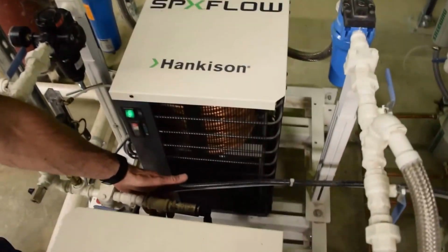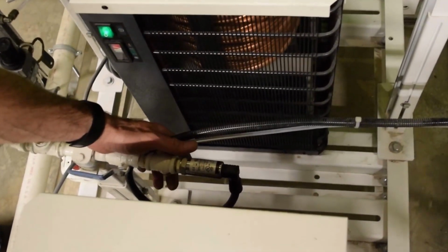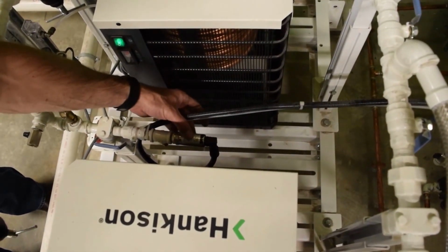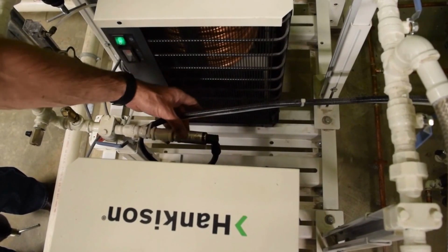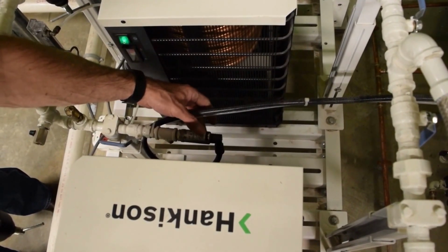Down here in between the dryers you have a valve that's open, and you'll hear a slight hissing sound coming out of this orifice down here. We want to hear that constantly. That's allowing fresh air to pass by the dew point probe, which is right here. That dew point probe is giving you the accurate real-time dew point reading on the display on the HMI screen.